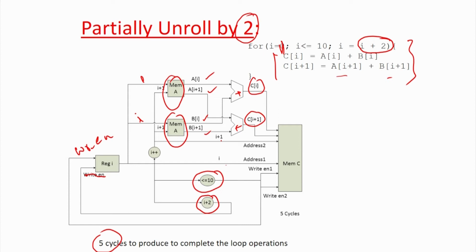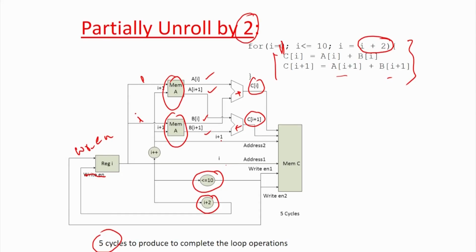And if you want a middle ground, when 10 cycles is too much and generating 10 adders is too much, then you go for an intermediate trade off by partially unrolling and then pipelining, right. So, this is a design choice you have to decide based on your requirement, but you have to understand that all the synthesis tools have this kind of facility. So, you have to choose the right option for your design based on your requirement.